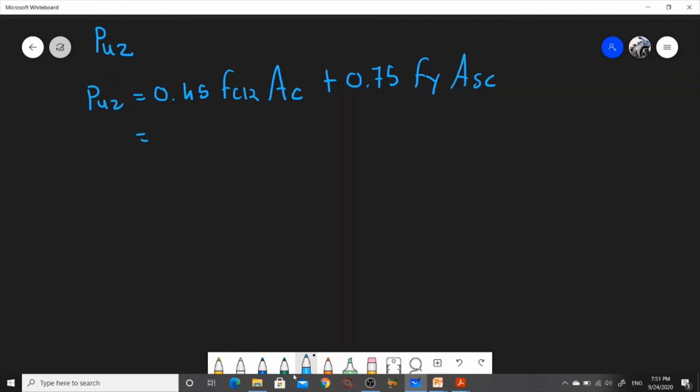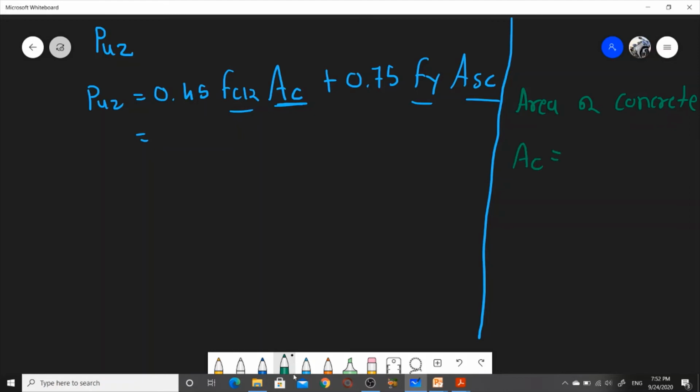We have FCK, FY, ASC, but AC is missing, so we are going to find out AC. AC means area of concrete. We will find out AC by AG minus ASC.